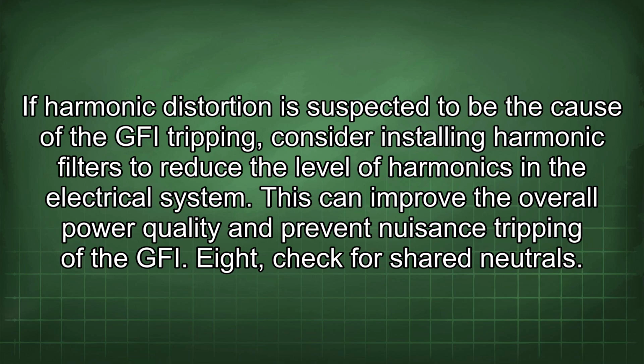If harmonic distortion is suspected to be the cause of the GFI tripping, consider installing harmonic filters to reduce the level of harmonics in the electrical system. This can improve the overall power quality and prevent nuisance tripping of the GFI.